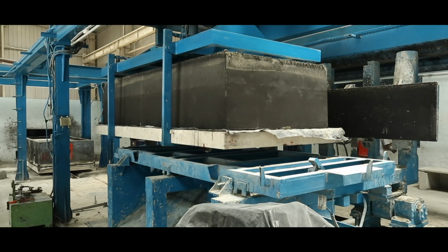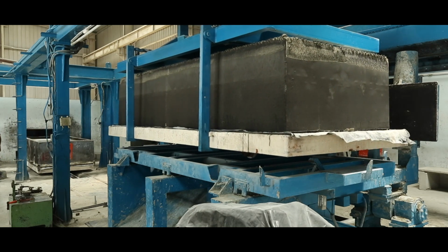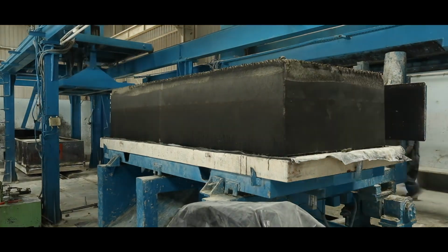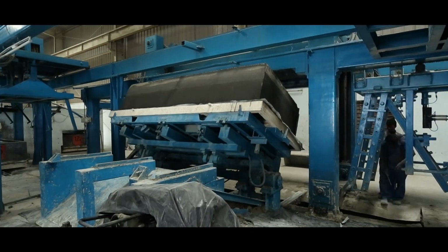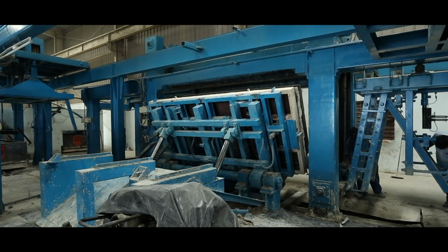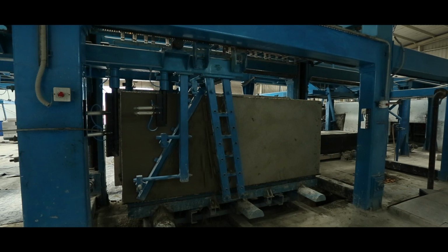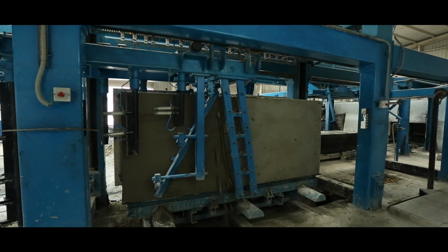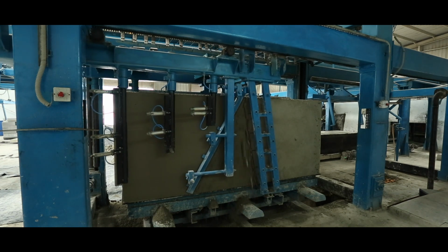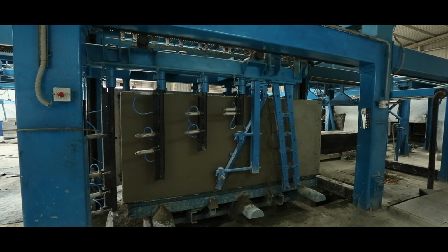On the cutting line, the cake is passed through a sophisticated cutting machine where the cake is cut in two directions to yield blocks of required dimensions. The cake is tilted to facilitate cutting in other direction. The cutting is done by special wires and designed for accurate smooth cutting. The extra grown material is removed at sides during the cutting process, and this green stage material is returned to a collection tank, where again it is converted to slurry and reused in the process.